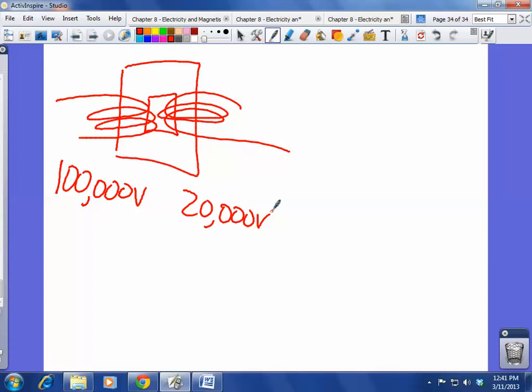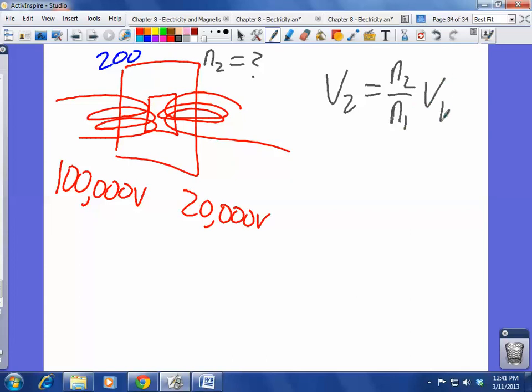In this case, I'm going to say we start off by wrapping this around 200 times. And I want to know how many times I need to wrap around here to go from 100,000 to 20,000, sorry. Why don't you guys take a minute and try this one. I'll put this up here. V2 equals N2 over N1 times V1. So see if you can identify each of those parts and see how many times you need to wrap that around. Okay, we'll take a minute. Help your neighbor if you were too quick.